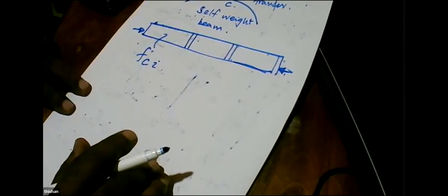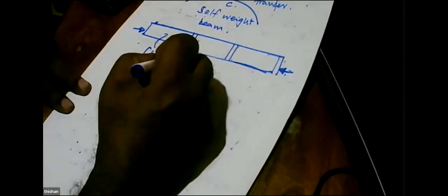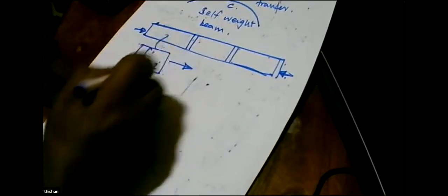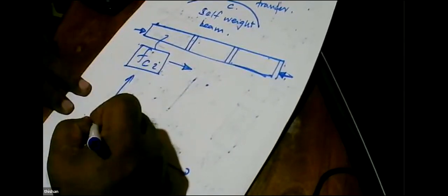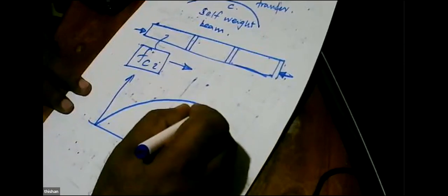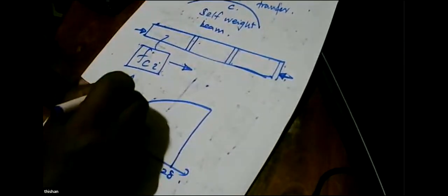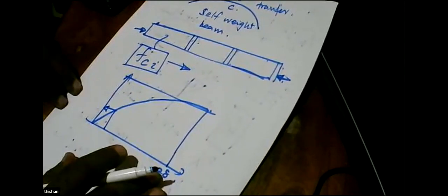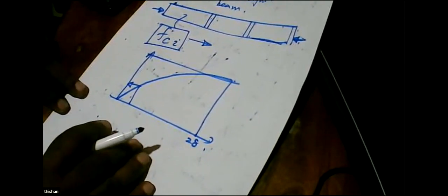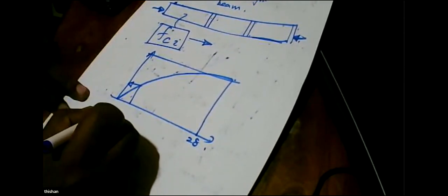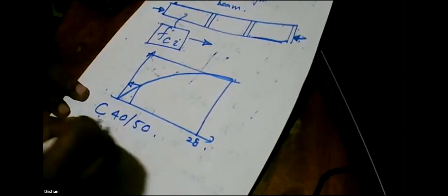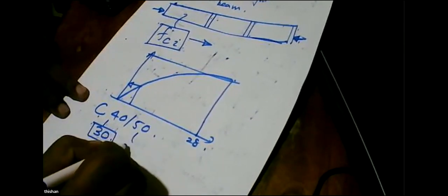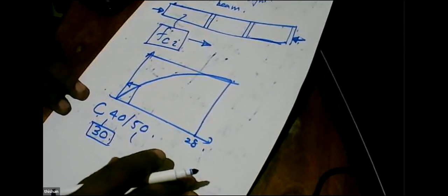So what we do is, we have to allow some compression, but we are in the strength development curve of concrete, and after 28 days, we might get some good strength, but we are here, somewhere here. So we may not have all the strength that we need. So if you are using C40-50 concrete, at the transfer we might specify the concrete should reach about 30, or here corresponding something like 35.